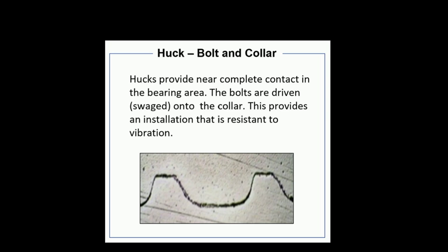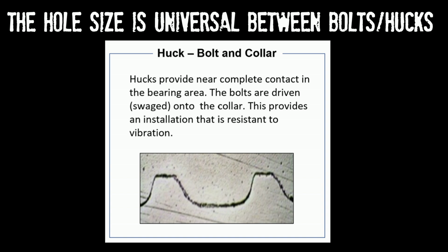Huck bolts are installed using a proprietary instrument calibrated for clamp load, not torque. Clamp load is the tension applied to fasteners like Huck bolts during installation. Unlike torque, clamp load remains constant and doesn't require maintenance. This ensures fasteners stay secure, preventing loosening due to vibration and improving frame reliability. If component relocation is needed in the field, the Huck can be cut off and replaced with a bolt.